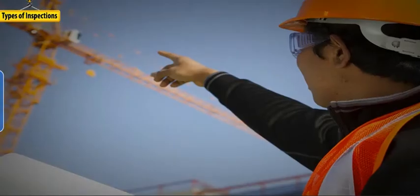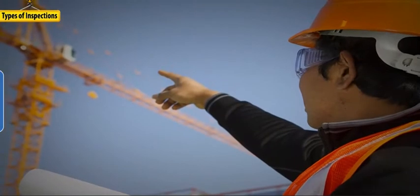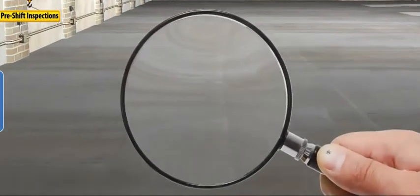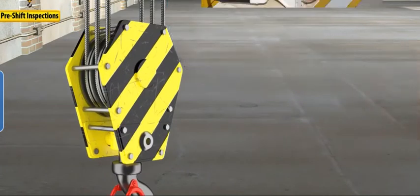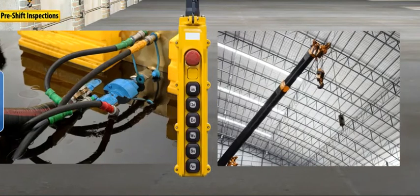However, you should always be on the lookout for potential damage and mechanical problems, even if you notice them outside of a normal inspection. Before you begin putting your crane to work for the day, you'll need to do a pre-shift inspection from the floor, including the hooks, pulleys, cables, hoist drum, hoses, hydraulic equipment, and control mechanisms.